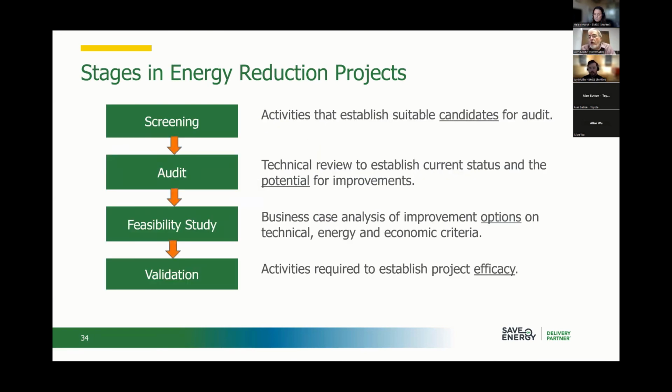One thing you do have to watch out with cog belts is that you might end up with a noise problem, and that's one of the things that you can run into. There's a high-pitched noise. It's kind of a pass frequency on the cogs and so on. So that's something that you may have to watch. Inside an HVAC or an air handling unit, there's enough insulation and other stuff that's probably not an issue. So maybe it's more of an issue if you've got a freestanding fan someplace.